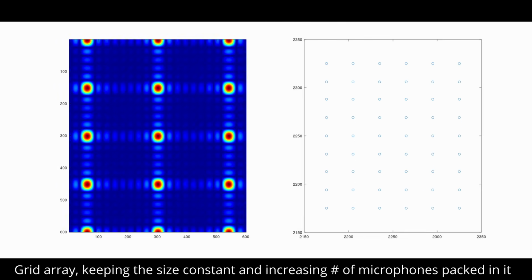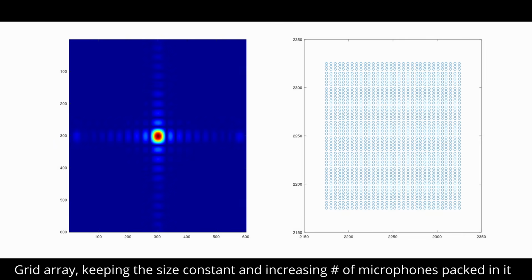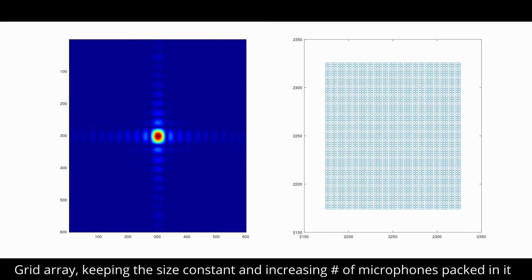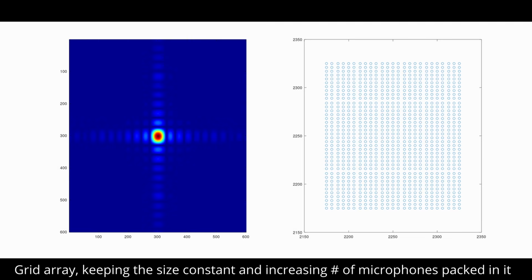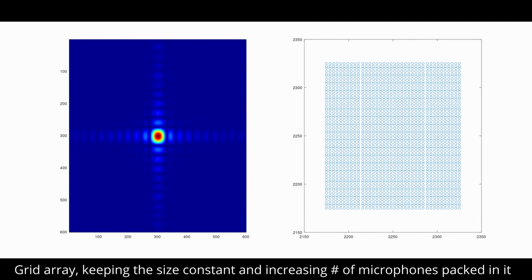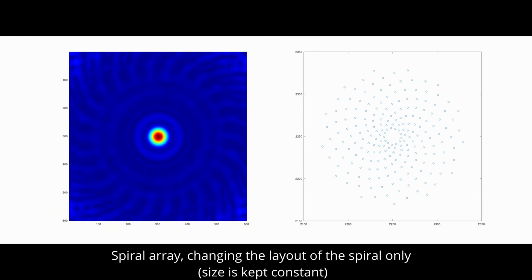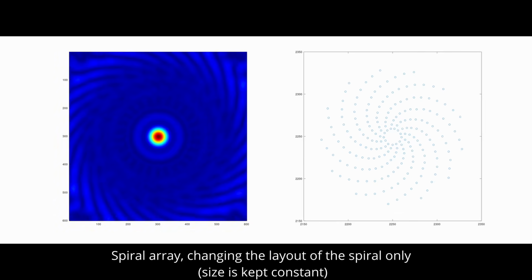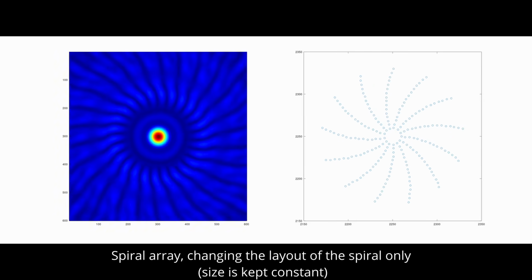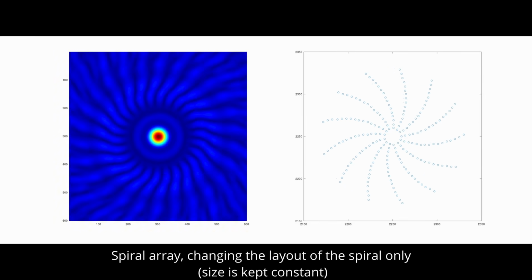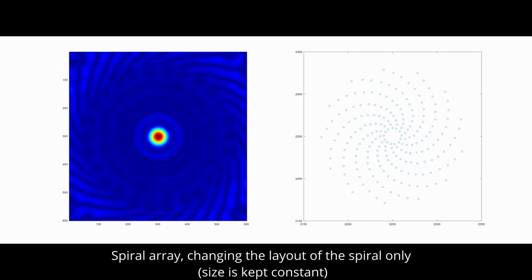That's not a coincidence. The shape of the microphone array directly affects the shape of the resulting artifacts in the image. It's related to the 2D Fourier transform of the microphone positions. If you understand how those work, this should be pretty intuitive. If not, at its most basic, a Fourier transform is a sort of way of extracting patterns from raw data. So because of that, any regular patterns in the layout of the array will produce significant artifacts in the image. So we want an array without any simple repeating patterns, especially not on a grid.